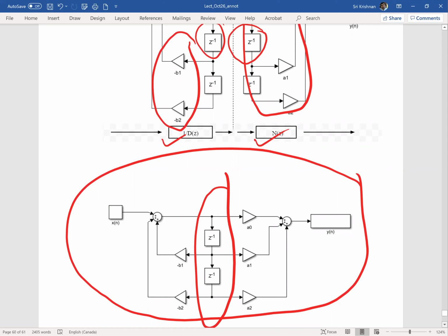You might think, what would be the big deal of saving delay elements? Obviously, we are reducing the latency in the system. And in practical applications, the filter order that we are considering is normally of a larger order. When the order is big, then we will have more of those resource requirements. So optimizing this at a block by block level really provides an overall efficiency in the design.